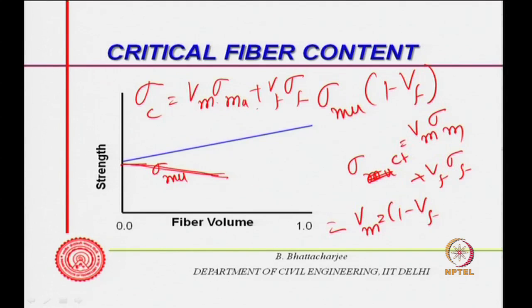straight away. But supposing my fiber is weak, then what will happen? This will actually be a lower value, this will reduce the strength. So, as I go on increasing the fiber, you are replacing a stronger material by a weaker material.